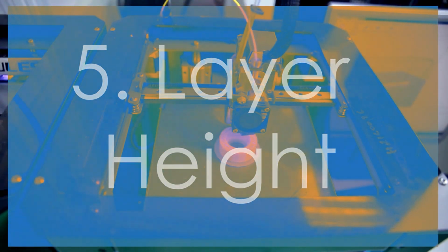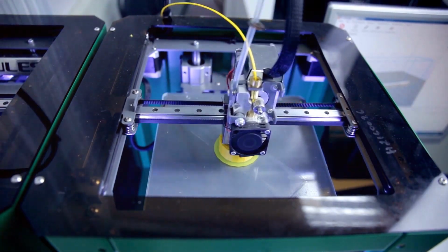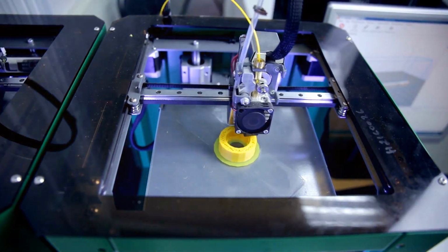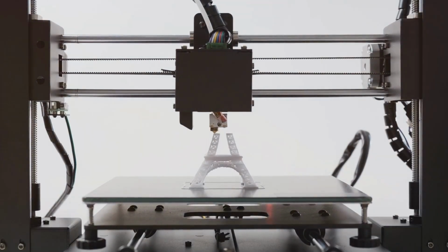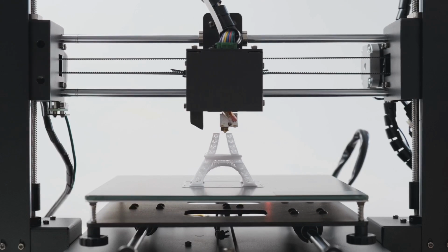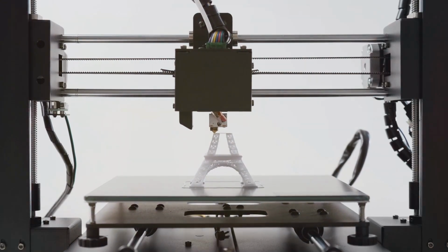Layer height refers to the thickness of each individual layer of filament laid down by the printer. Smaller layer heights result in smoother and more detailed prints, while larger layer heights can speed up the printing process.